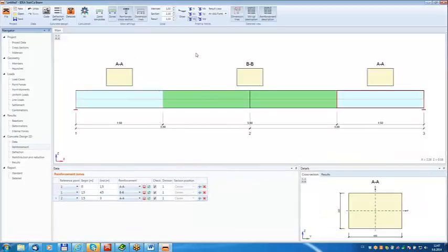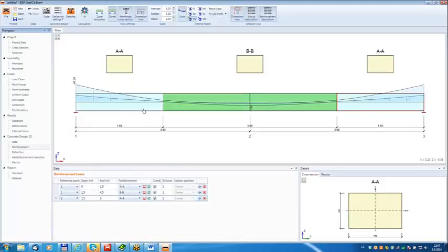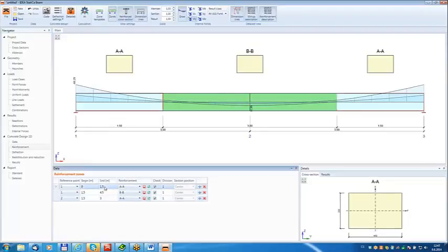Now we entered this reinforcement. We work with straight beam because it is more convenient for the user. I want to draw these bending moments so that I can decide which zones I should use. So possibly because of bending moments I will have different zone, different reinforcement above the supports, and different here because we have different bending moments here.